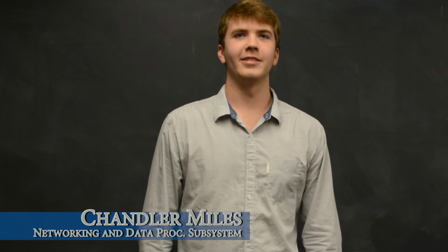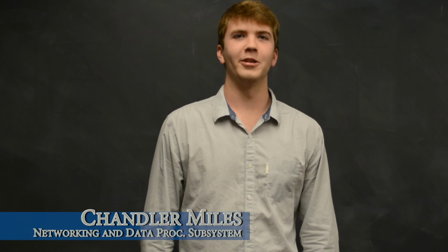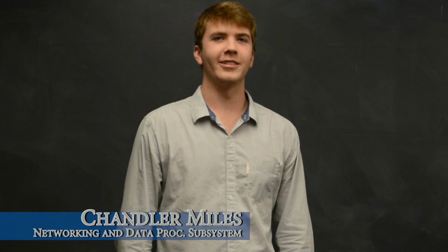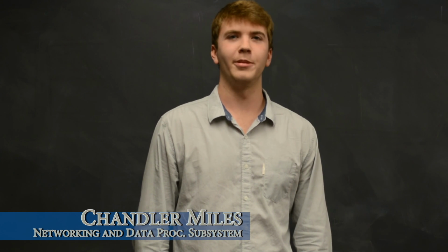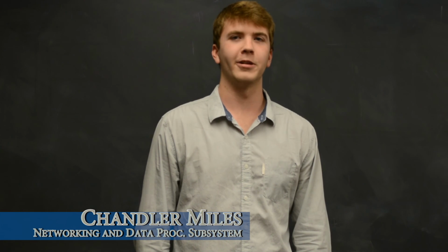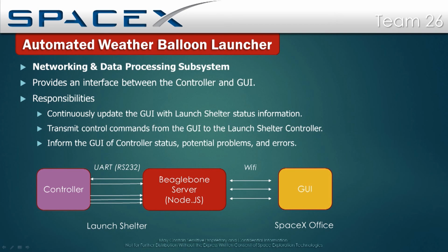The networking and data processing subsystem consists of a single BeagleBone Black microcontroller which is located inside of the balloon launch shelter. It is connected serially to the mechanical controller and communicates with the graphical user interface over Wi-Fi using Node.js and Socket.io. The networking and data processing subsystem is responsible for three things: continuously updating the GUI with launch shelter status information, transmitting control commands from the GUI to the mechanical controller, and informing the graphical user interface of controller status, potential problems, and errors.